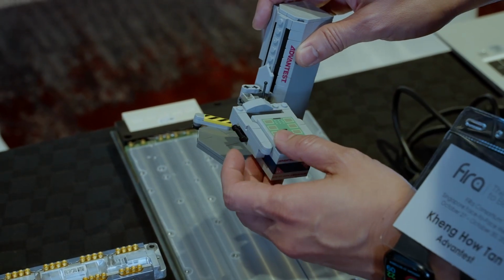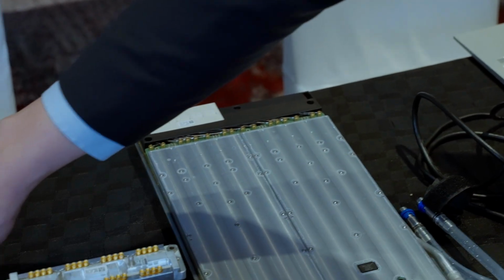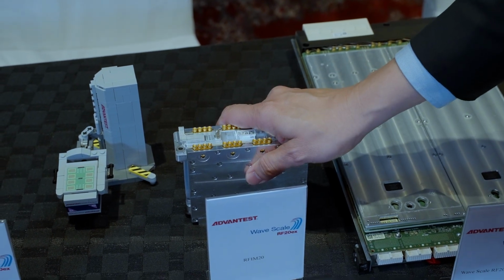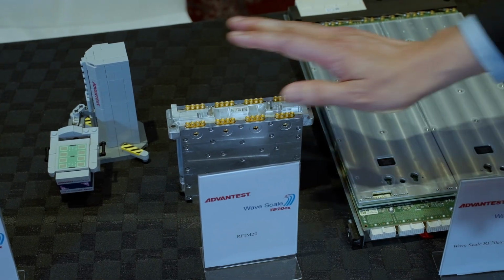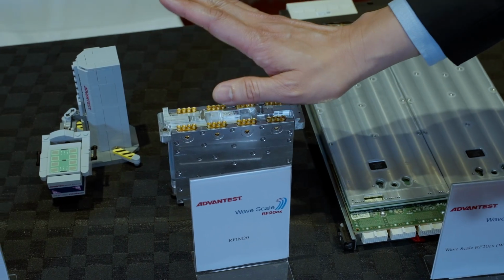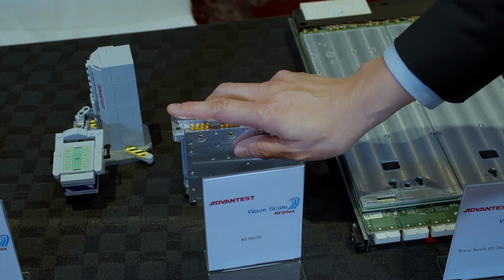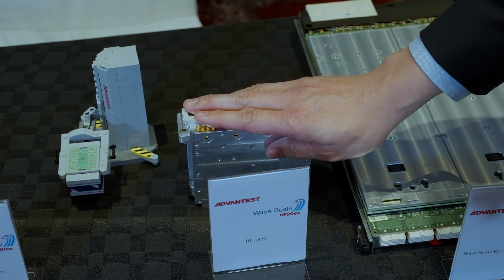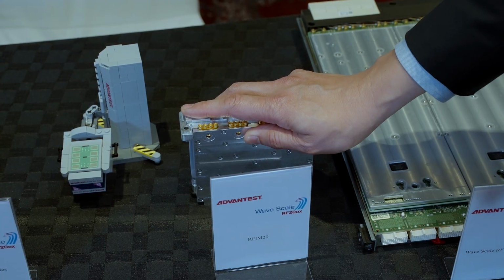And for the test head, you will have a cable to bring it to the interface. We call it our RF interface here. And this interface, one of the RFIM, or RFIM interface, has 32 ports, and each card is able to support 2 RFIMs, which is up to 64 ports. Be aware that each of the ports has the same capability of 50 megahertz to 20 gigahertz with a 2 gigahertz bandwidth, bidirectional. This makes it very flexible for the user to use our channels to perform multi-site testing.